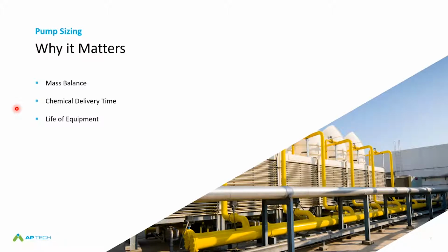The other part is your chemical delivery time. Particularly with shot dosing, we're wanting to slug in a bunch of chemistry very quickly. So it kind of has the tidal wave effect. Let's just say with a biocide, if you need to get 5 gallons of biocide into the system, but you only have, let's say, a half gallon per hour pump, well, it's going to take you 10 hours to get that 5 gallons in. So you want to make sure that you have the appropriate size chemical pump in order to deliver that chemistry in an appropriate time frame.